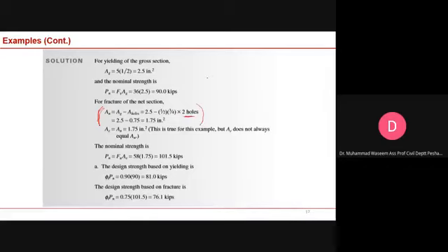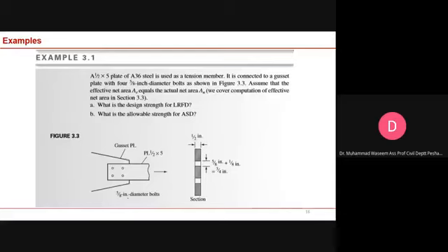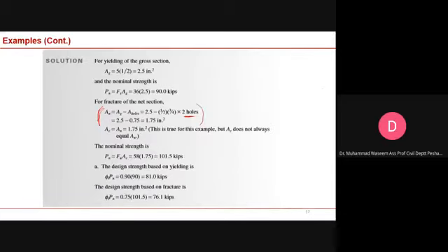Firstly, if you go back, the diameter of the hole is, let me write it down here, okay? This is the diameter of the bolt. The diameter of the bolt is 5/8 inches. What should be the diameter of the hole? 1/8 clearance. So this should be 6/8, okay?